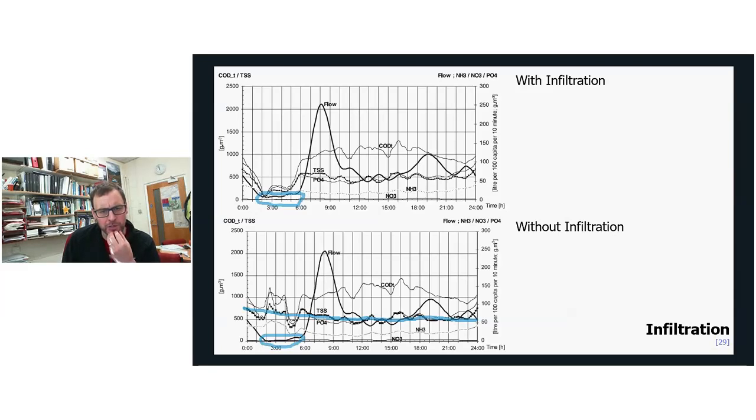I've been in sewage systems during the evening, and it's quite interesting. It's always interesting, but it's quite interesting in that during the evening, because there's less foul inputs to the system, the water is much clearer, and because proportionately more of the water in the sewer is infiltrated water as opposed to water that's come from domestic properties, the temperature also goes down as well.